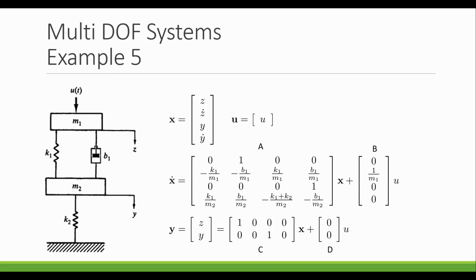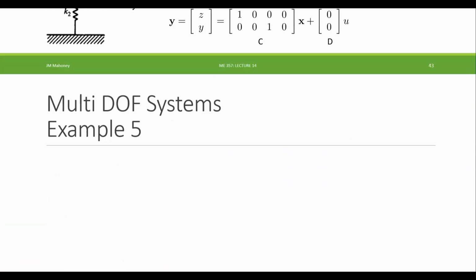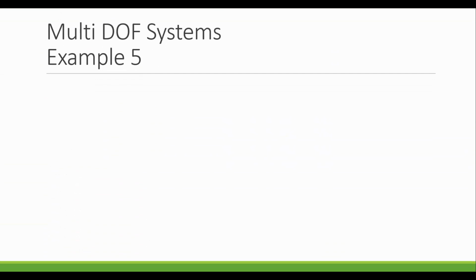Now what we can do is move on to the analysis, really more of the spirit of this unit. All right, so what can we do with the state space model? Well, really I'm going to use it and go into the transfer function form, because that's going to be easier to work with when looking at the next step, our analysis. So recalling back when we first looked at state space, we saw that we can go between state space form and transfer function form. Analytically, we can do it using those ABCD matrices, or we can use the ss2tf function in MATLAB, which I'll look at later.